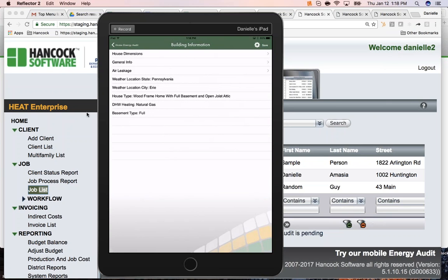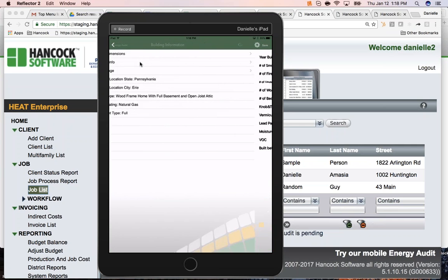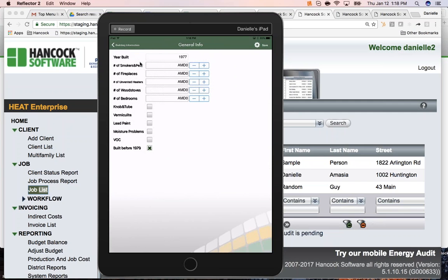And the other part of the main section that you might want to touch on is, in addition to energy modeling, we've built some calculators in, like the ASHRAE 62.2 2013 ventilation. Art, is it the number of bedrooms, or which of these inputs are used in a calculator such as the ASHRAE 62.2 2013? It would potentially be the number of bedrooms. It depends on the difference between the number of bedrooms and the occupants that are recorded in the record.